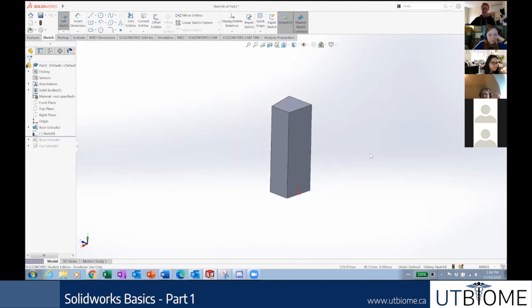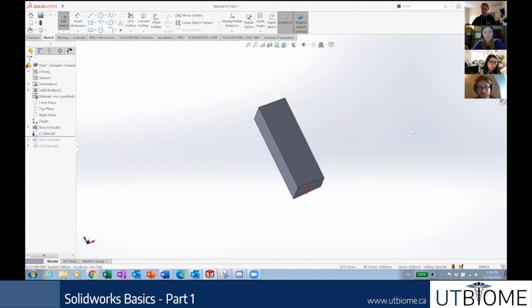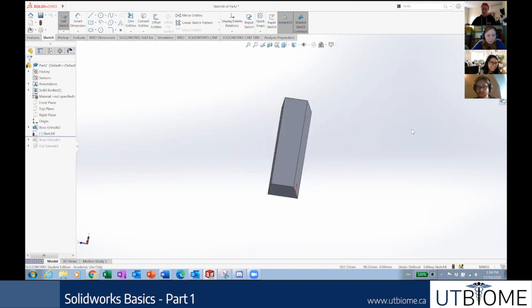There are some more advanced controls that nobody uses except for me. You can click the arrow keys and stuff will rotate. You can also hold Control and click the arrow keys and stuff will move. I will show you one time where this will be useful, but I think that will be next week. I just learned something new in SolidWorks.